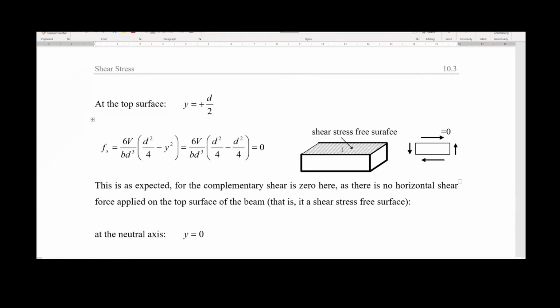There are no shear stresses in here, because in order to have a shear stress, you need to have another element producing some sort of friction. And because this top surface is absolutely free, because this is just, let's say, a beam subjected to its self-weight, it's impossible for you to have any shear stress, because you don't have any other structural element producing it.